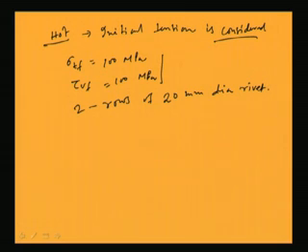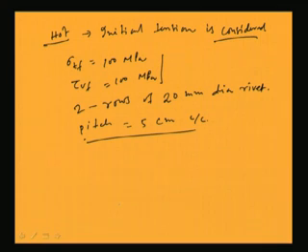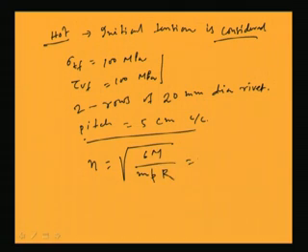And let us assume the pitch distance as 5 centimeter center to center. So, pitch distance we are considering 5 centimeter and 2 lines of rivets have been given. So, we can find out the total number of rivets from this formula, 6M by mpR. So, from this I can find out, right.